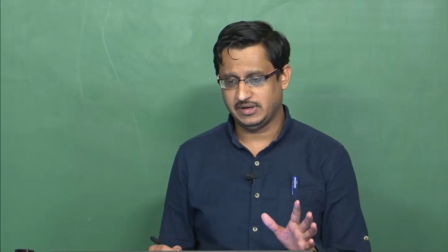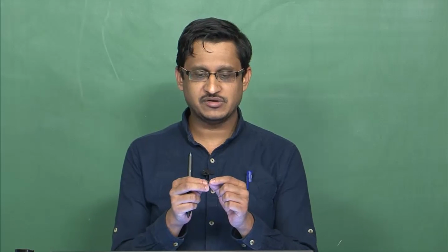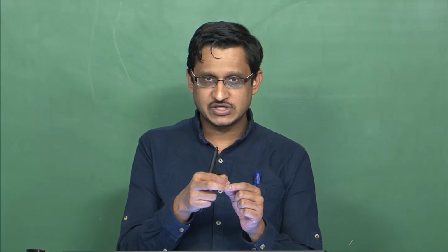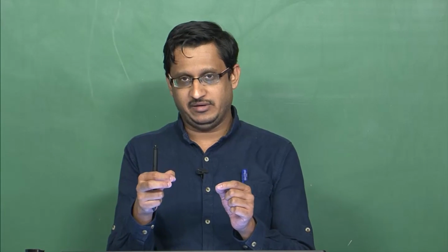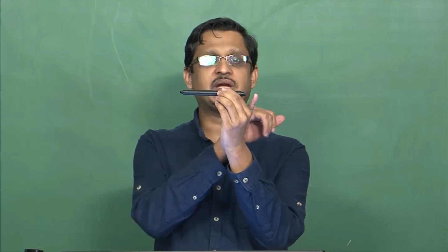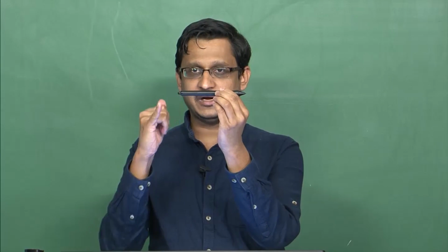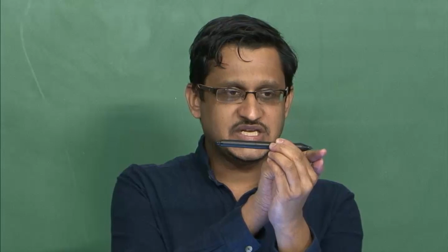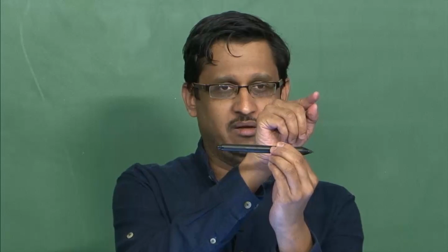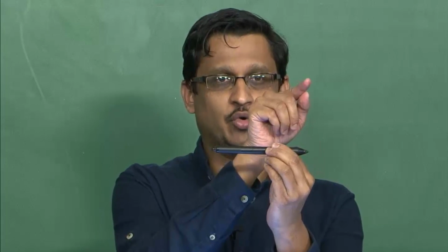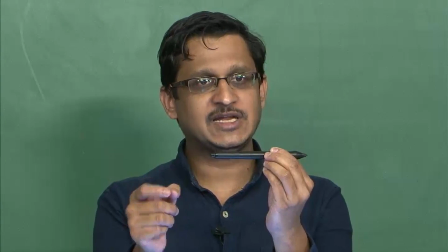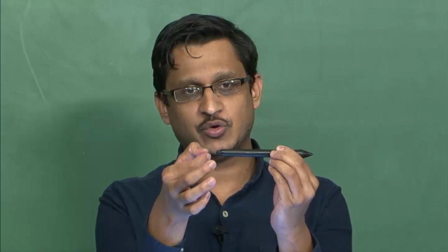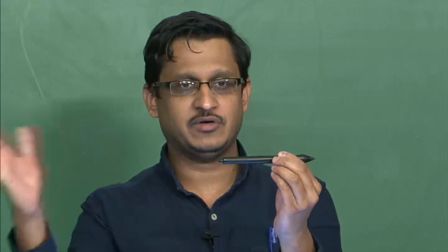You basically understand one thing, right? When we consider a particular piece of wire as a wire, we are not concerned about the time that is required for the voltage at one end of the wire to travel to the other end. That is, if I consider this as my wire connecting, say, one integrated circuit here and another integrated circuit at this point, of course it will not be like this, but imagine that way. When the IC changes its state, maybe it goes from 0 to 1, changing the voltage level from 0 to 3.3 volt. If the load has to correspondingly change, if the load is just an inverter, for example, then the inverter input voltage must change accordingly, right, so that the output of the inverter must change.